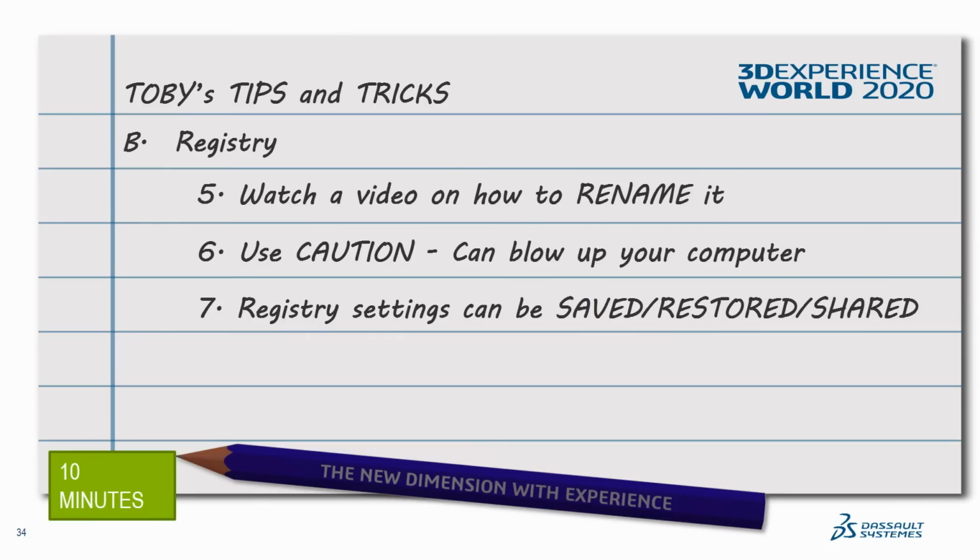Great question. So the question was, what about the SolidWorks copy settings wizard, right? So the copy settings wizard generates a file called a .sldreg. If you right mouse button on the folder in the registry and you say save or export, it generates a .reg. The sldreg is basically the same thing. Not exactly, but close enough. So that's what you're doing. You're exporting your registry key. You're just doing it through a wizard interface.